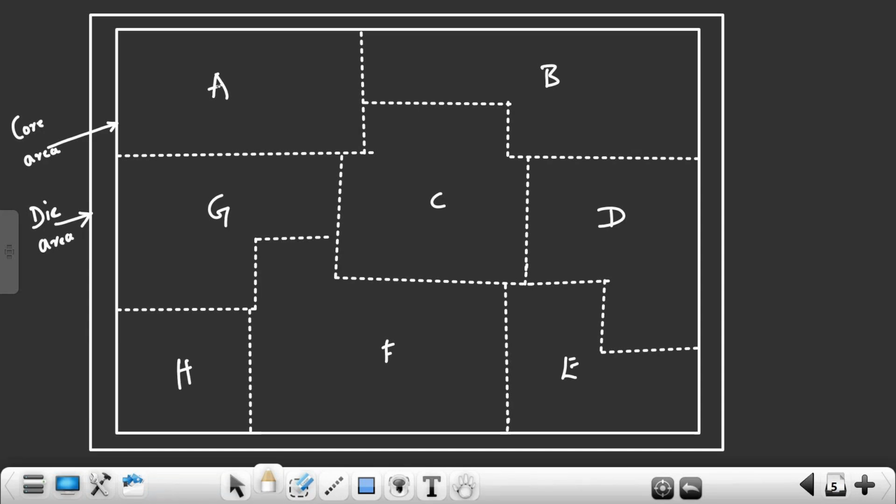Each block is given to each engineer. For one bigger IC, they split it, right? Minimum they will split into 40 blocks. I'm talking about big ICs, at companies like Qualcomm, Intel, AMD, Nvidia. The big chips are split into a minimum of 40 blocks. So each engineer does physical design for each block. For your block, they will give a netlist and other required files. For each engineer, they'll give a separate netlist, right? Now you do the physical design for your block.